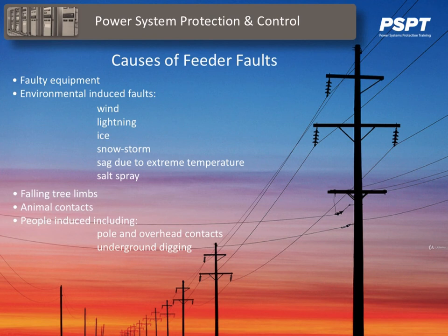Faults occurring in the distribution system must be sensed quickly and immediately, and isolated to prevent hazards to the general public and the utility personnel. Protective relays are used to sense short circuit conditions caused by faults in distribution protection schemes, and the use of proper schemes and settings can help to maximize sensitivity and selectivity.